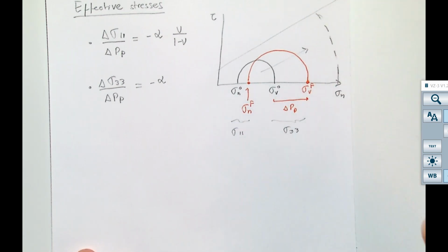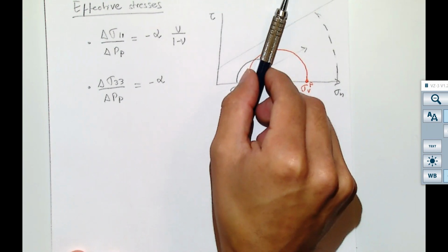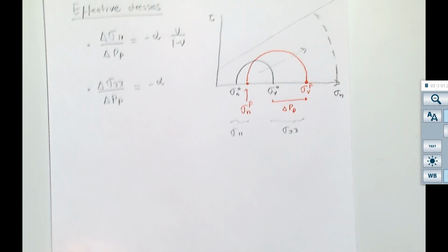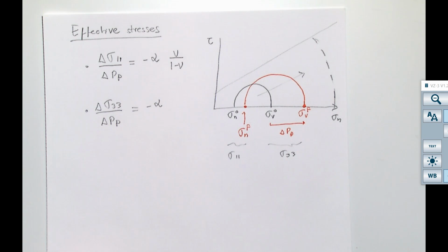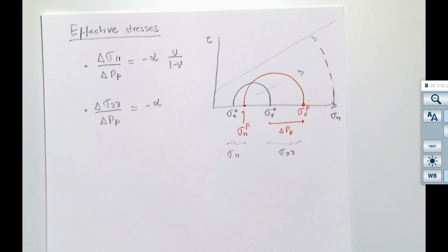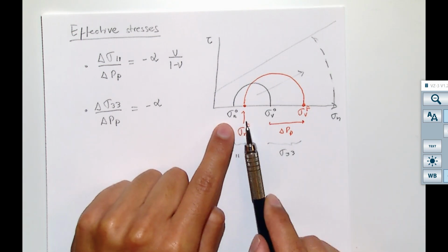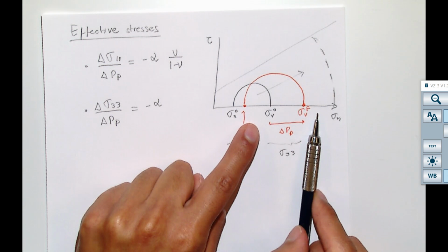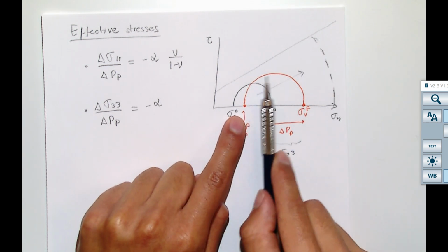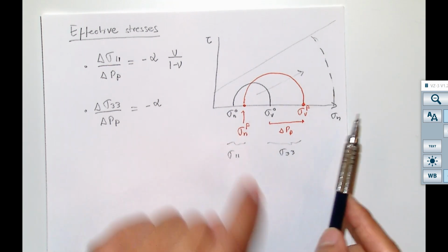And this one is the shear one. Some people suggest that sometimes also you can go into this direction and get into shear. That's a little bit under debate, but some people argue that you can also go into shear by depletion. So, very important, remember, depletion is always going to increase effective stresses, both horizontal and vertical, but the horizontal stresses are going to increase less than the vertical stresses. And that's going to make your Mohr circle get bigger, because the difference between horizontal and vertical effective stress is going to be larger.